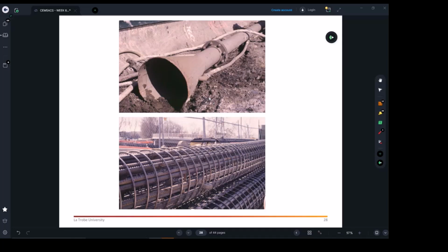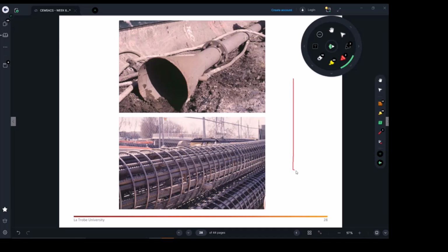When the engineers design their loads for a 900 diameter pile, this bearing needs to be really flat. The trimmer will help in doing that, because this gives us a good hundreds of kilonewtons to resist whatever load it's taking, beside, as we said, the friction resistance.